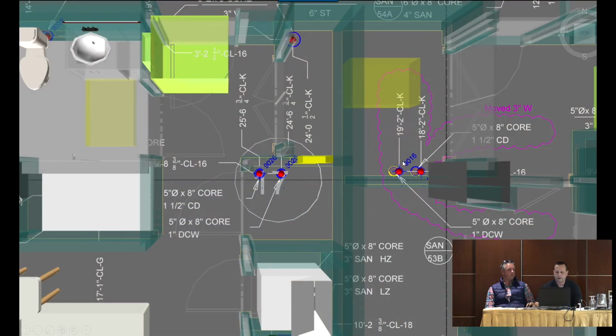You'll notice here on the right, 0.9016, there's definitely something wrong. The sleeve is actually west of the shot that we took in the field. But you'll also notice a note that said moved 3 inches. As a result of the GPR review process, the core was relocated 3 inches to the west. The annotated documents are updated, and now Davis can easily see that change.